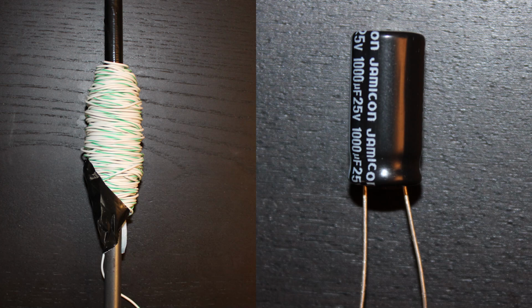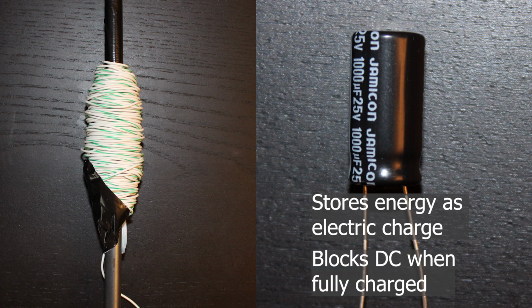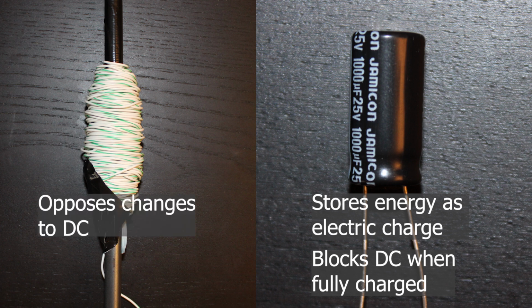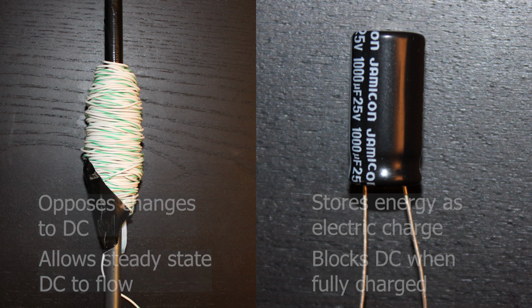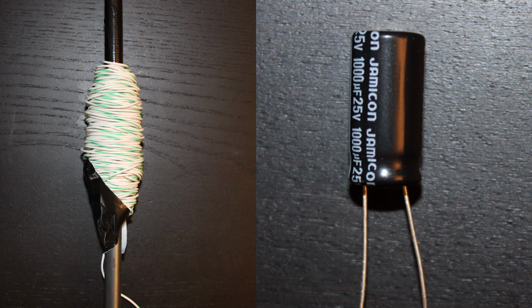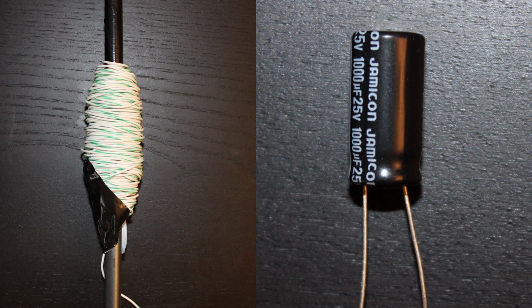It's parallel to the capacitor, except that a capacitor stores energy as an electric charge and blocks DC once it's fully charged, whereas the inductor initially opposes a change of current, but then allows a current to flow. Correspondingly, while a capacitor will allow AC, an inductor will impede it to a certain extent, and that will be determined by the characteristics of the inductor and the frequency of the AC. And this is something that we'll actually explore further in the next experiment.